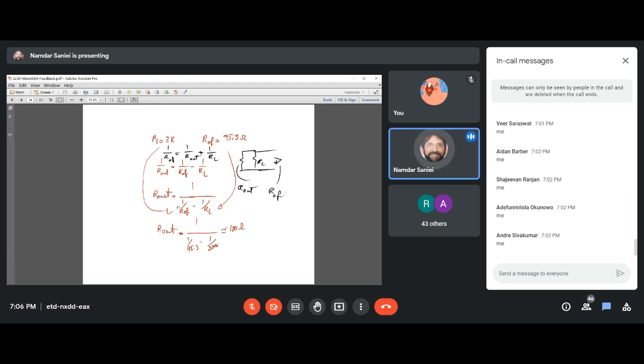And what we had in those other slides that you questioned, what is it or where is it coming from, is exactly from here. That's the same equation that we found there. This was for R out. The same thing exists for R in. Replace ROF with RIF and RL by RS. Then this R out becomes R in, which we call the true input resistance of the amplifier under feedback.